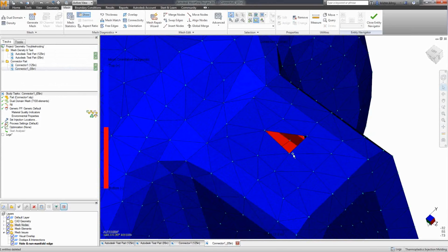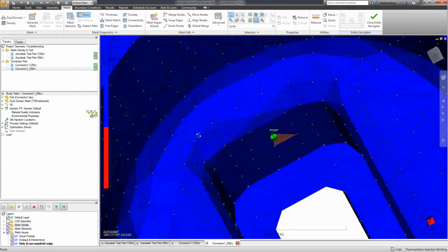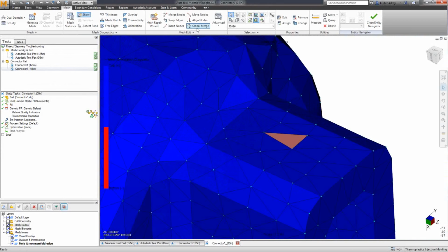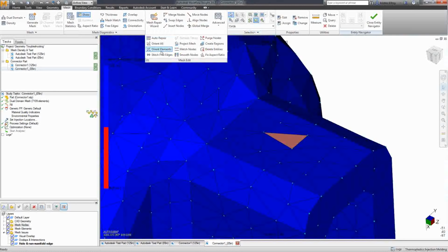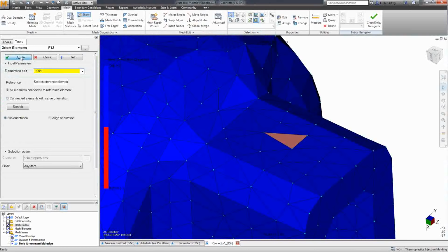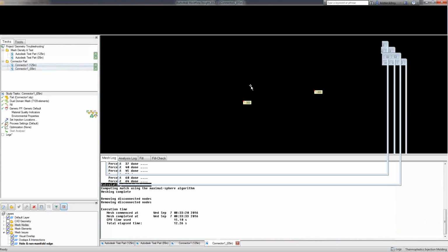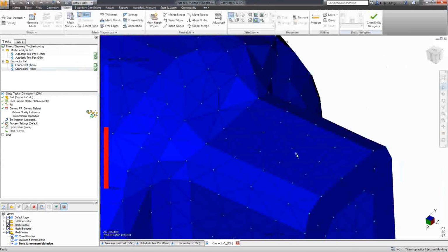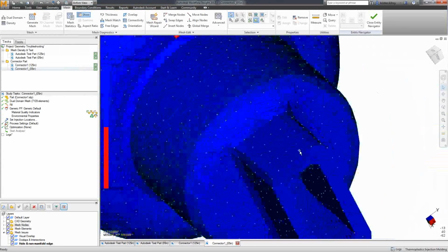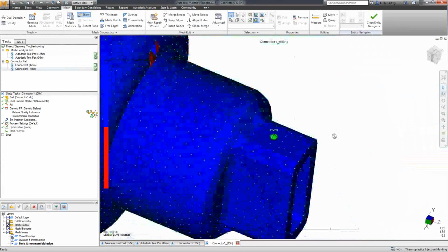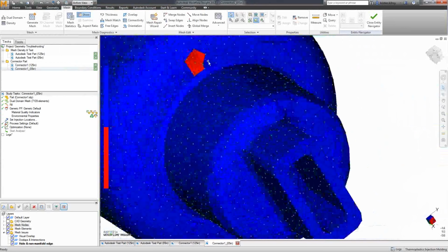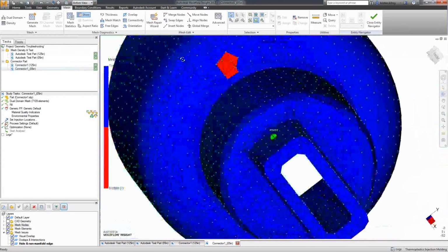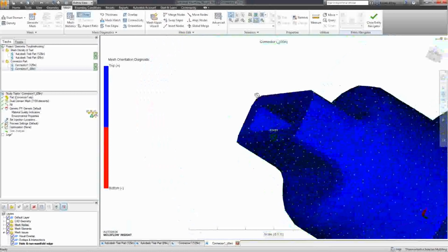So it looks like there is actually an overlap on there. And again, you'll find these different mesh issues whenever you're going to troubleshoot them like this. In this case, if we go through and orient again, there we go. All I did there was just delete the one that was on top of it, and for the second one, I just oriented it to match the others. And you can see down here is a hole that we can work with. Since we already worked on that, I'll let that go right now.